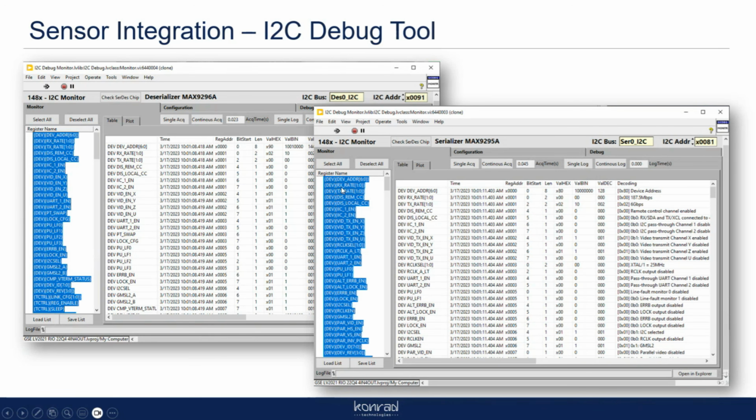He's got it so we have like a 100-page manual. It's insane. It's ridiculous. It's just pages and pages of registers and what they mean. All we see in LabVIEW typically is the value of the register address and then what the value is. We don't know what it means. So what Luis has done is reverse engineered that entire manual so that we can go in there and look for a certain register name, or we can go by value and see what it means. Like here, if we put 00, that means the error output was disabled, or lock output was disabled. There's all these different things.